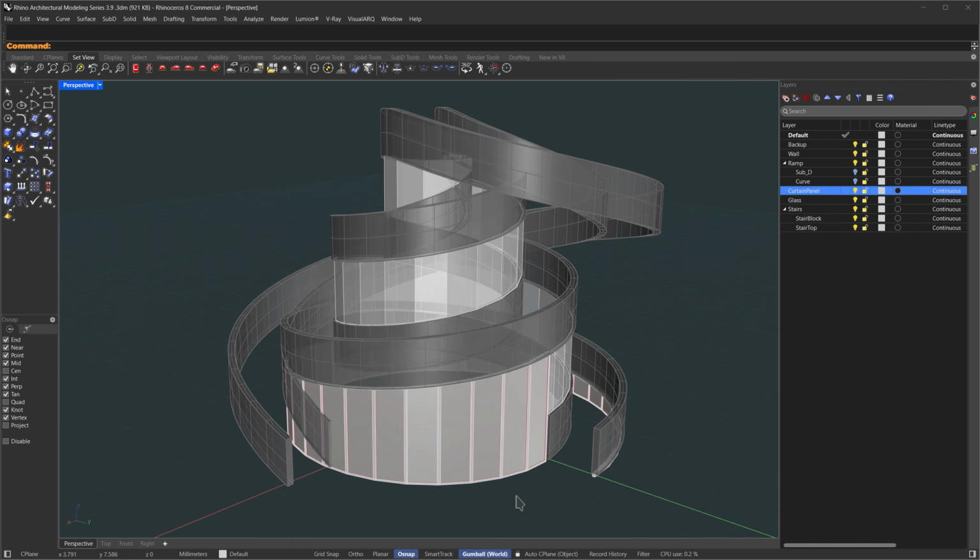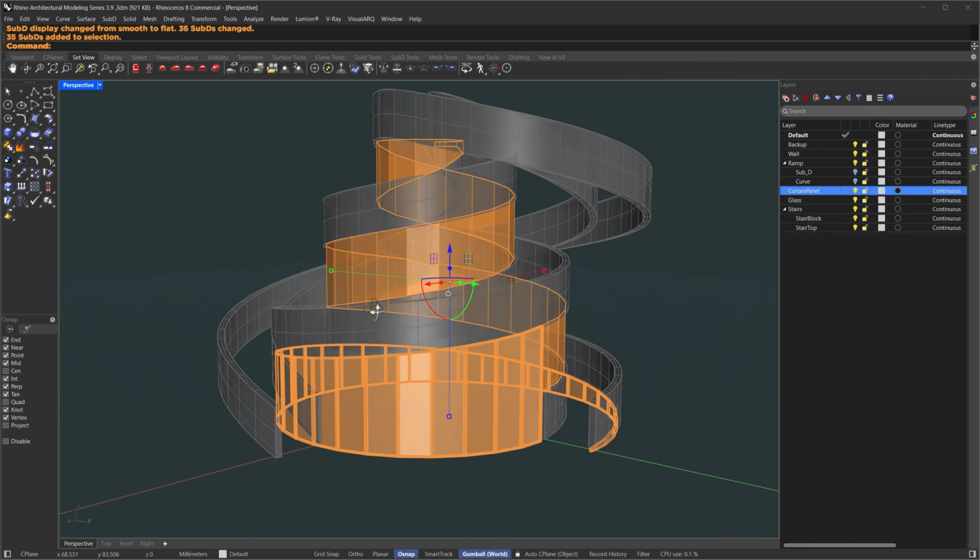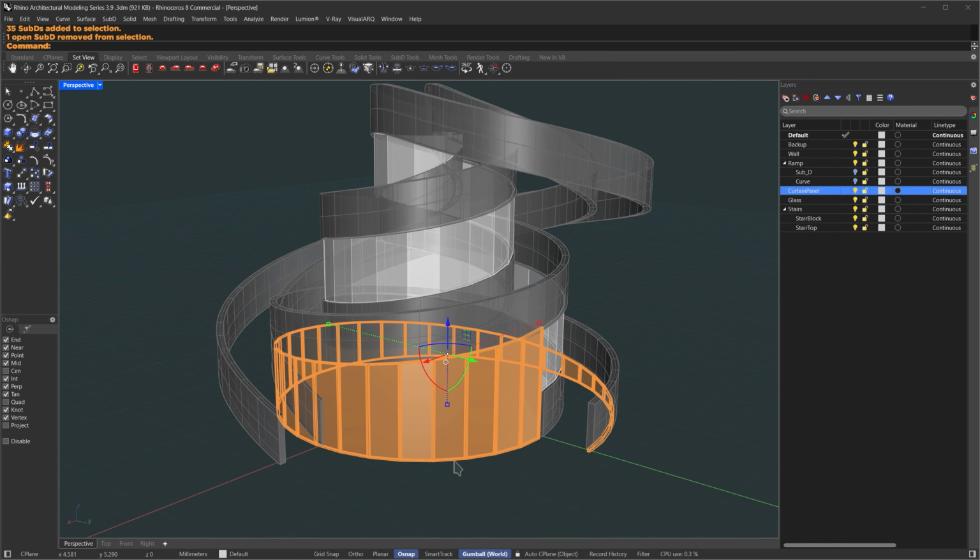If you press tab, you'll see the frame collapse. Let's keep the frame as it is. Select all of the sub D we just created, unselect the top sub D, and run extract control polygon. While the result is still selected, run the toNURBS command.